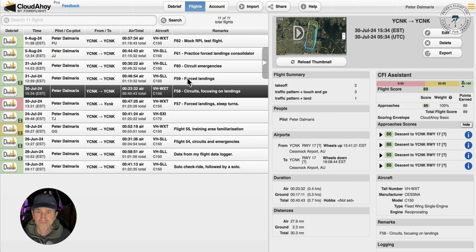So I'm not going to go through the details there, but I am making progress there, and the technique is to try and focus towards the end of the runway, use the cowling as an assistant to help me with pitching the airplane appropriately and at the right time as it's losing energy and the altitude is decreasing, to make sure that there is separation between the front wheel and the runway.